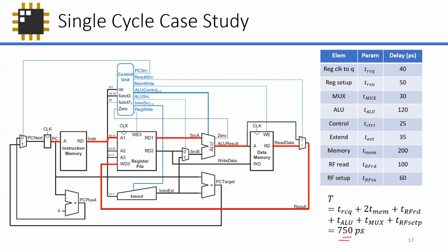That's the minimum period from register to register, because the register to register path is this register, and then all of this, one whole big chunk of combinational block, and then this is your next register again, right?